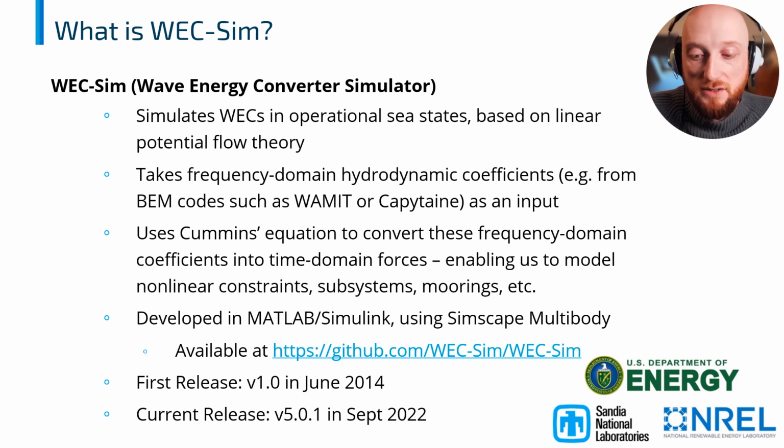It takes frequency domain hydrodynamic coefficients from BEM codes such as WAMIT or Capytaine as its main input. Then WEC-Sim uses Cummins' equation to convert these frequency domain coefficients into time domain forces. That enables us to model nonlinear constraints, subsystems, moorings, and so on. It's all developed in MATLAB Simulink, and it uses Simscape Multibody as the main solver. Simscape Multibody is also where the libraries of constraints and bodies are contained.